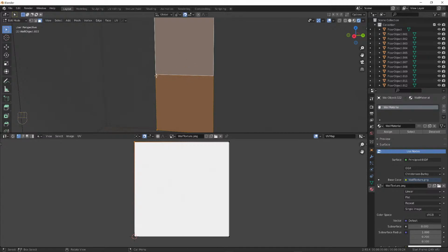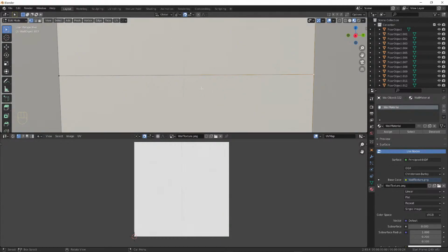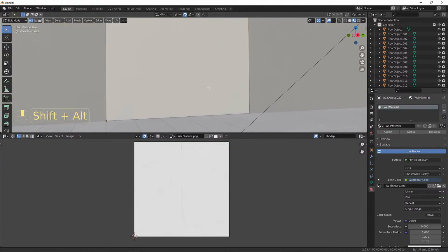What that's going to do is look at this overlapping vertice, remove the doubles and merge these 2 meshes together. So tap M here and merge by distance, and you'll see it's removed 2 vertices. And now if I select one of these, it's all joined together. And they both still have that same texture applied. It's a little faint, very subtle, but definitely it's there.